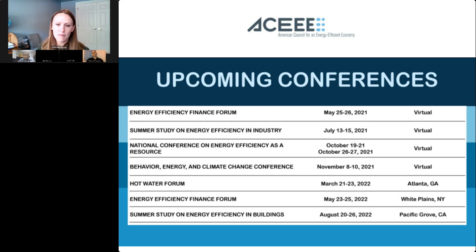Most of the controls that I was looking at were very focused on demand response. And we also talk about shifting load to when there's more renewable energy available, but you could very much wind up in a nice sweet spot where there's a lot of hot water usage in the morning, and you wait to reheat that tank till the middle of the day when it's both warmer outside and when there's more solar energy available on the grid. So you get a nice combination there, with better efficiency and a better source for that electricity.